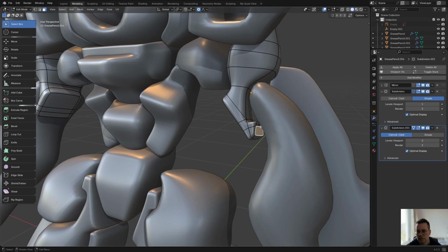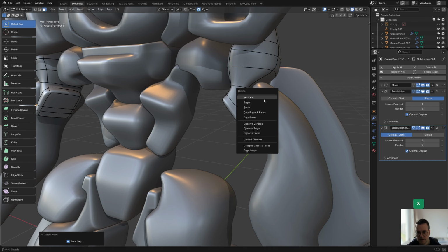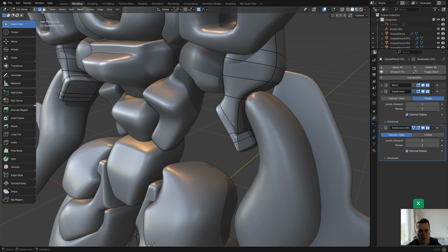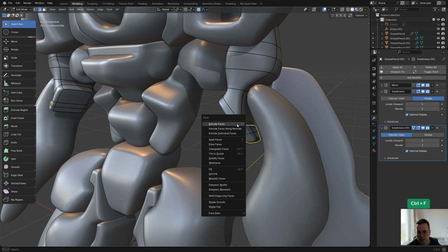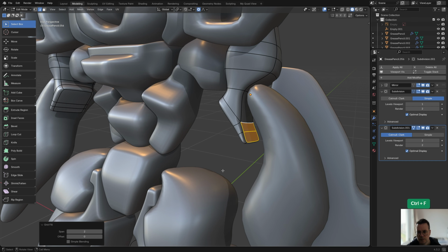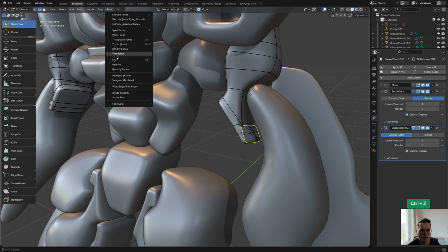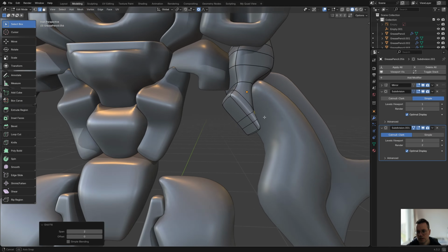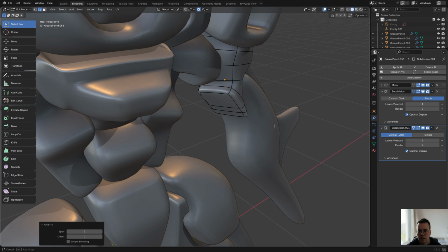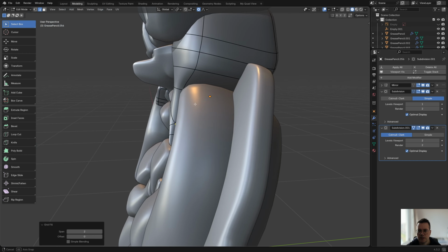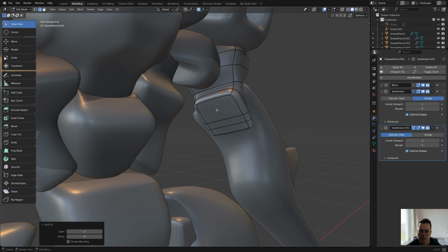And let's see, we can also select these two faces and press Ctrl and plus, and then just delete them. So X and faces. And then in edge selection mode, Alt and left click on this and press Ctrl F and then choose grid fill, or alternatively go to Face and Grid Fill, just so that that is filled again. And in this case, I want this shape to be a bit rounder. What I'm going to do is add a loop here.